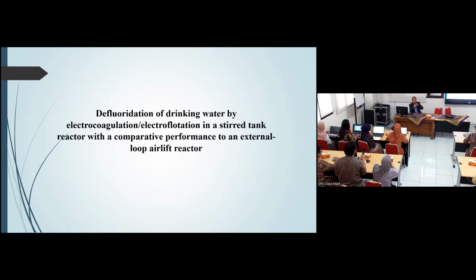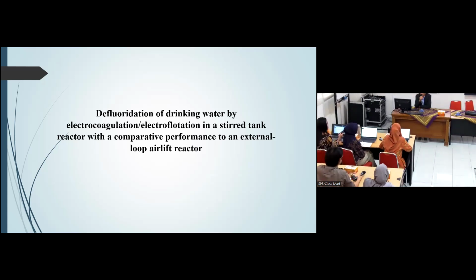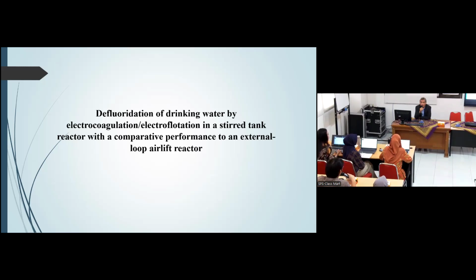Okay. Concerning the electrodes, there is Faraday's law. You know Faraday's law, that you can calculate. You can measure the loss of mass of the electrodes. So you design your reactor, and that's why we use a lot of electrodes, because with Faraday's law, you can exactly find the time needed to have, for example, 50% loss of mass. So we can master this aspect without problem.